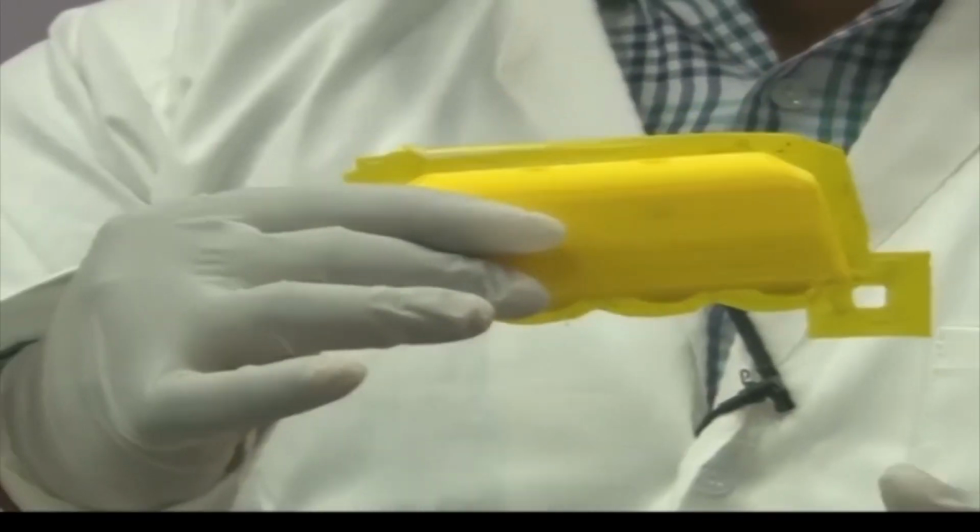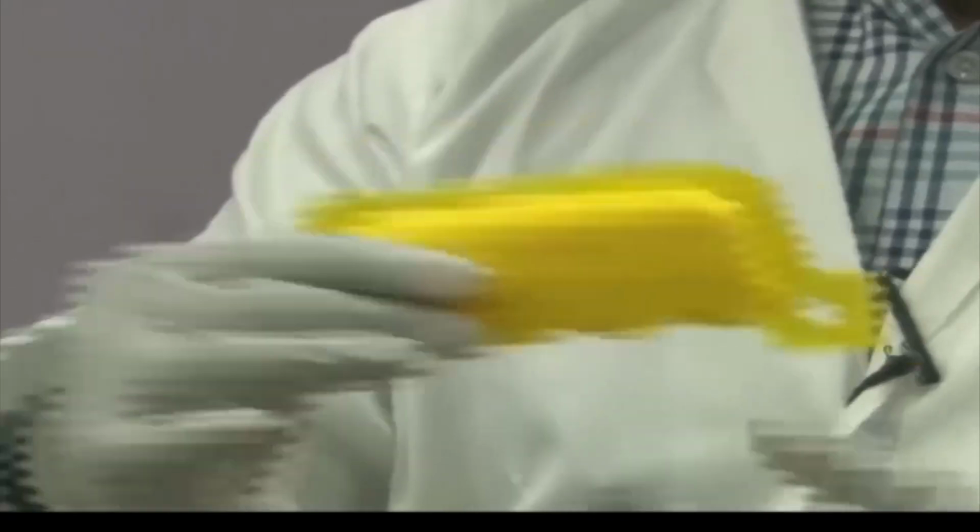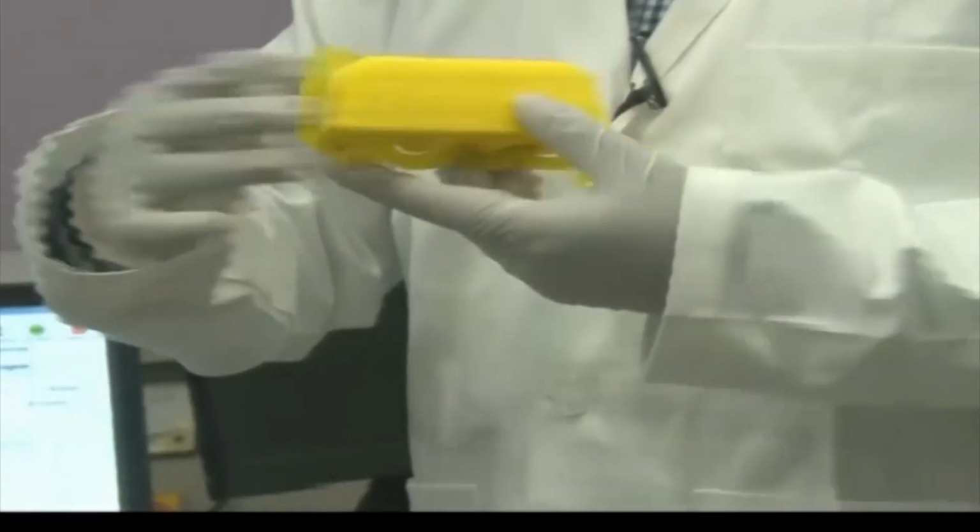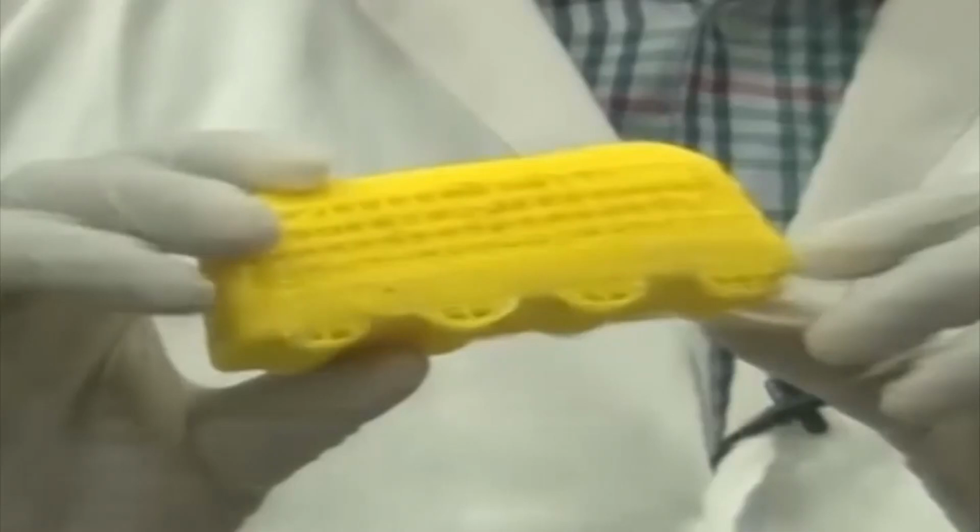Also we have more extra material here. Those are supports, and we will show you how when we remove them. We can remove brim by hand very easily, manually, and we can get the finished final product. If the CAD model is flat, it's okay. If it is not flat, if it has some inclination, as I said, what would happen? How would the machine take care of the printing? It would provide some support.